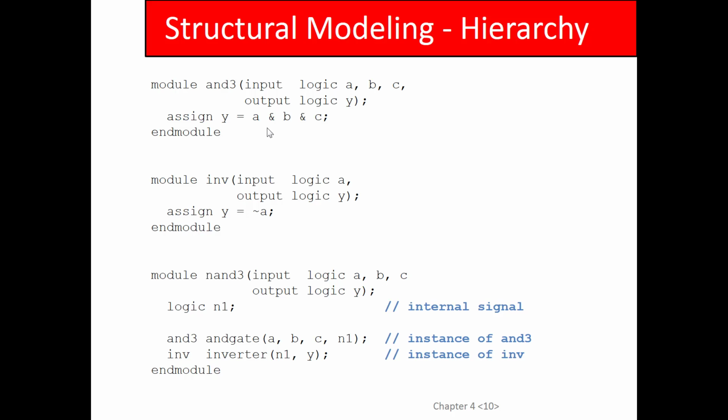And by the way, this is something else I should point out. In Verilog, it would be declared as a wire, not as a logic. So if you see wire, that's because it's Verilog. But in SystemVerilog, they renamed this logic. But it's just a 1-bit signal. I mentioned last time, when I say 1 bit, by the way, the value of that could be a 0 or a 1. But it can also be an X, meaning undefined, or Z, high impedance. There's a couple other values besides just 0 and 1.